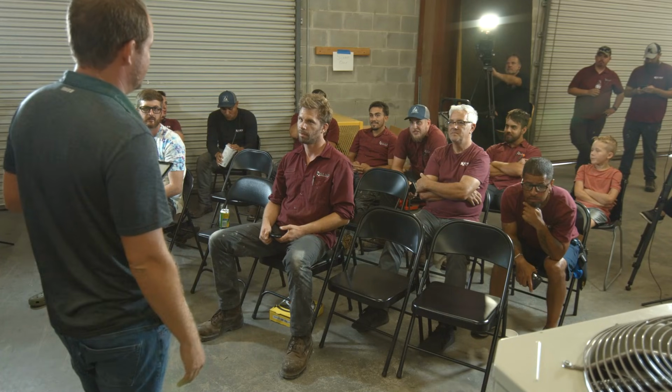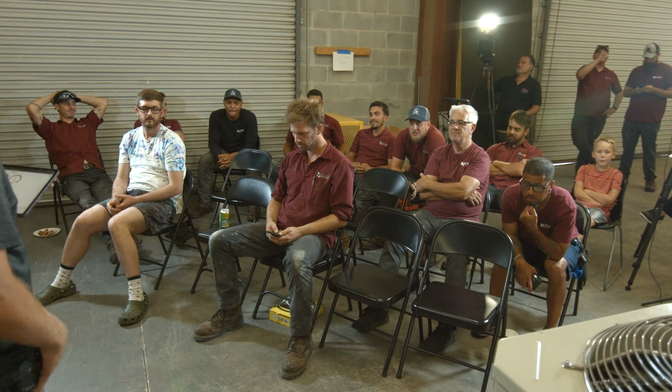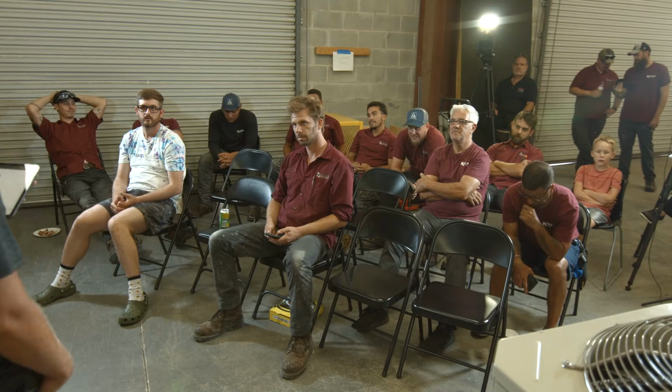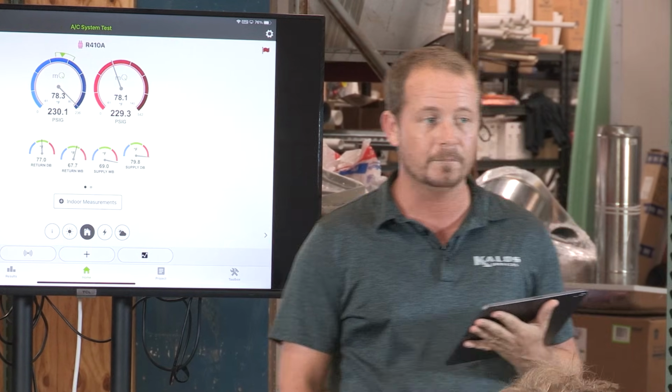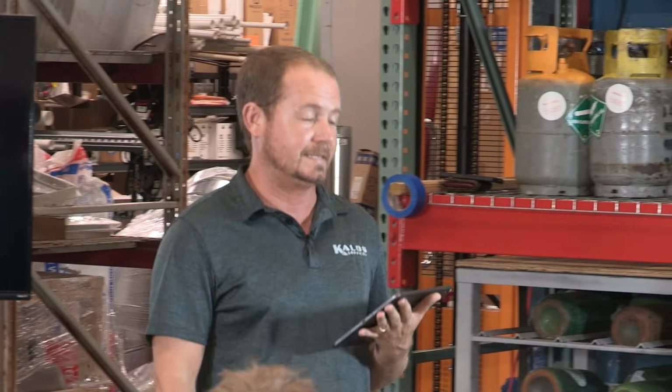Oh, okay. Go ahead. Mass. I like mass. I like a good conversation about mass. What's going on to mass when you have lower airflow? The volume stays the same, the mass decreases. Okay, the volume of what stays the same? Refrigerant. The volume of refrigerant entering the compressor, being cycled through the system stays the same, but the mass is decreased. Why? Lower load, lower heat content. Because there's lower pressure, right? Lower pressure in a contained system means less mass if the substance is the same. So it's lighter. Easy way to think of it is low suction pressure means lighter gas. There's lighter gas coming back to that compressor.